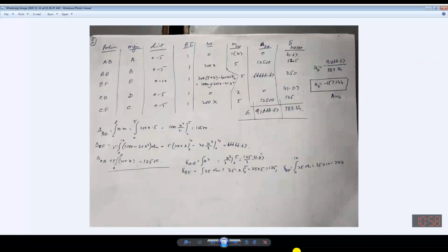Now when you multiply these two, as I have shown you, displayed over there, capital M, small m, 0 to L. This is giving you the displacement. On the same lines, only one displacement is needed as far as the actual structure, the primary structure, the actual loading is concerned. This will be delta DH, and if you multiply M into m, then you need to apply the limit, and over there it will be integrated. There will be dx over there.